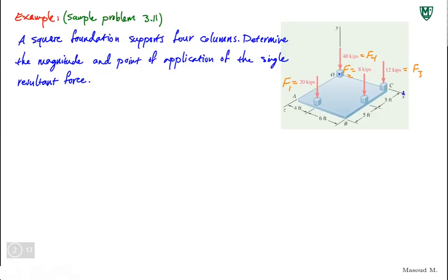So considering that this is our coordinate system, this is X, this is Y, and this is Z. So let me use the color I usually use to answer. All right, so we start with, let's represent first forces. Keep in mind, I'm looking for FR, the resultant force, and I'm looking for MR, the resultant moment. In this case, I need to specify which point, so I'll take it about point O. So I'm looking for these two first. First step, find the equivalent system that only has one resultant force and one resultant torque or moment.